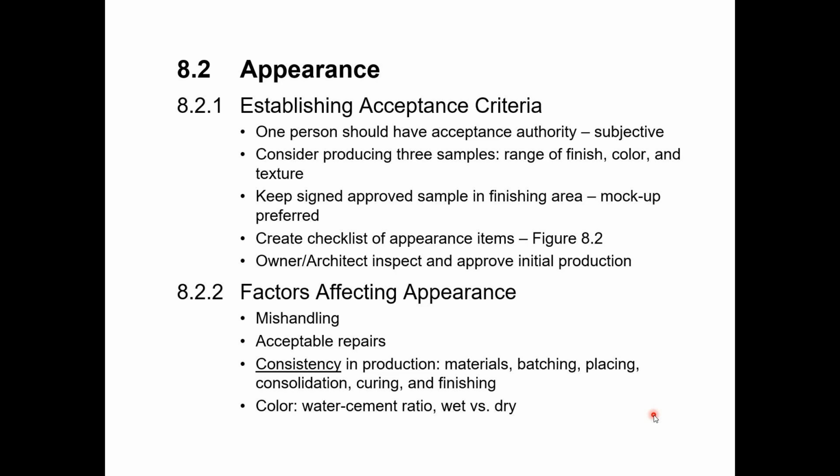And once you arrive at a decision, you keep those panels in the yard, near the finishing area, so that the people doing the finishing can regularly look at those as a touchstone to say, okay, we're not drifting too far away from what the target is. They can compare visually. Here's the panel we're producing for the day, and just over my shoulder are the accepted panels that the architect came and looked at. So let's make sure we're matching those as best we can.